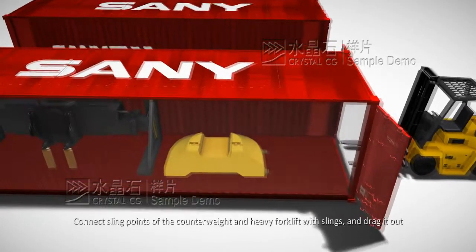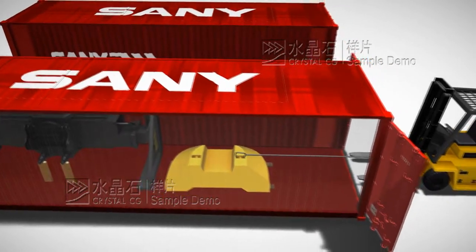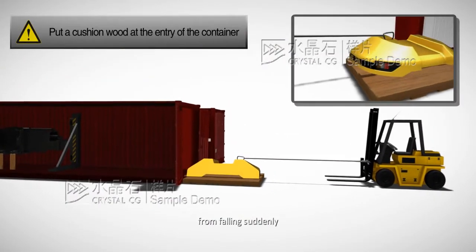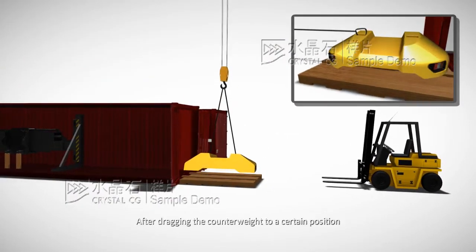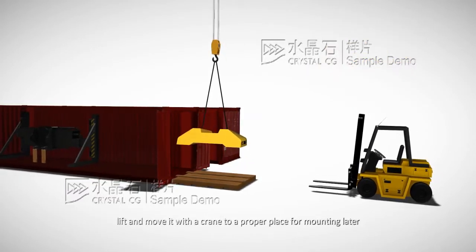Connect the sling points of the counterweight and heavy forklift with slings, and drag it out. Put a cushion wood at the entry of the container to prevent the counterweight from falling suddenly. After dragging the counterweight to a certain position, lift and move it with a crane to a proper place for mounting later.